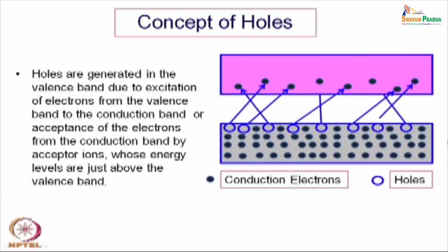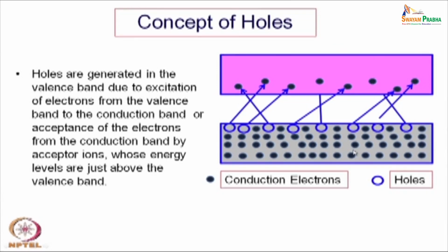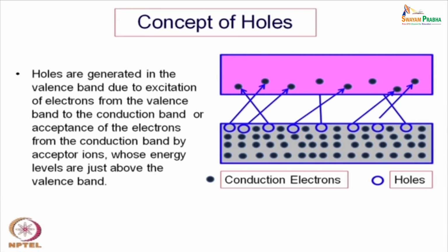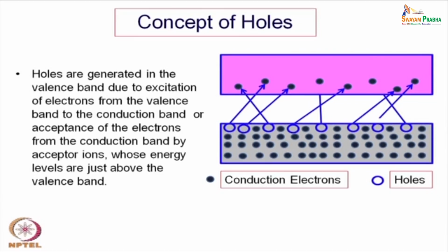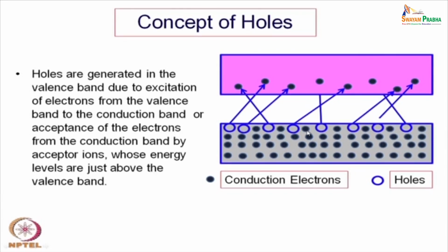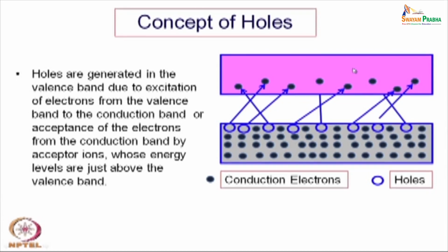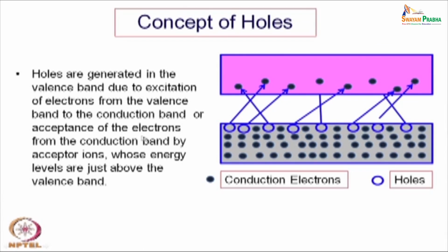This is the band gap, the energy diagram for the host material, in which we have added some impurity, and that impurity incidentally may have a very strong affinity for the electrons. So, it has a tendency to absorb electrons, then that will absorb electrons from the valency band and also create holes. So, corresponding electrons will not be created in the conduction band, but the holes will be created in the valency band.